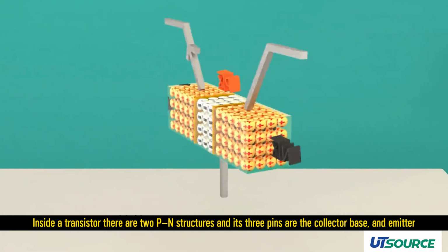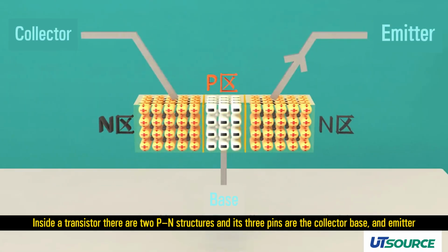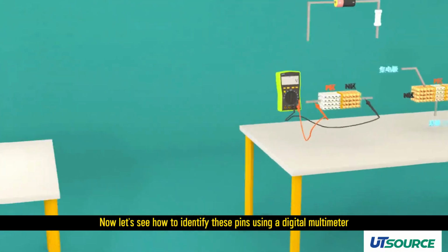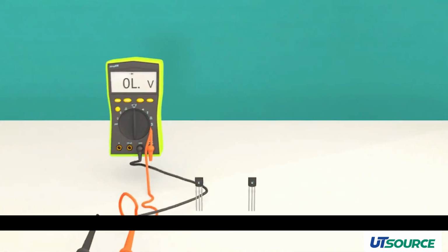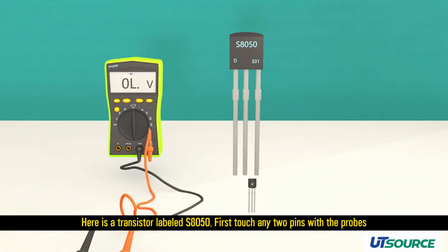Inside a transistor, there are two PN structures, and its three pins are the collector, base, and emitter. Now let's see how to identify these pins using a digital multimeter. Here is a transistor labeled S8050. First, touch any two pins with the probes.